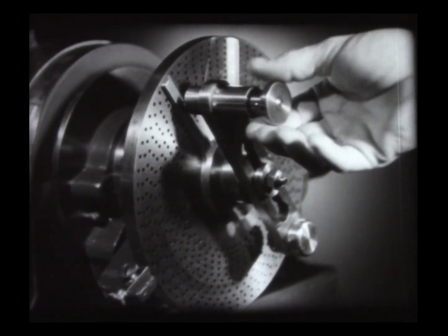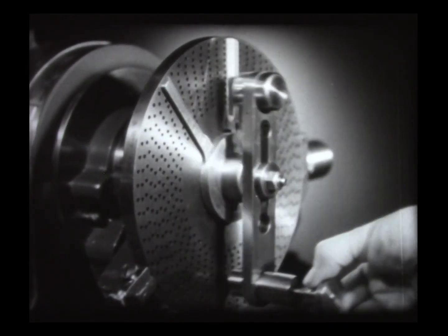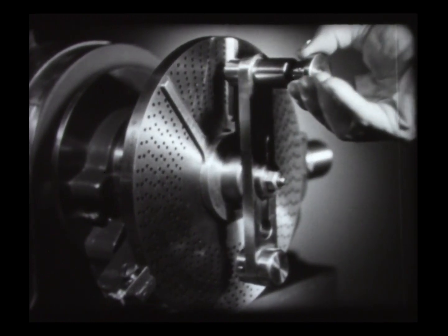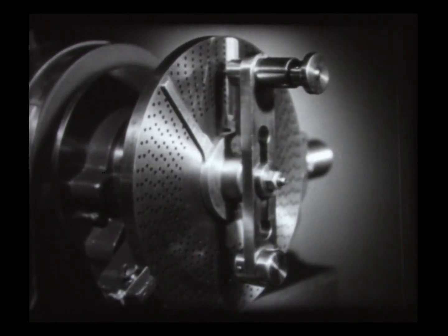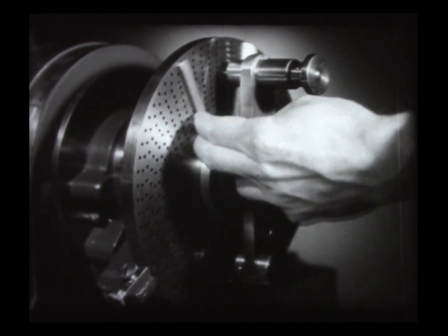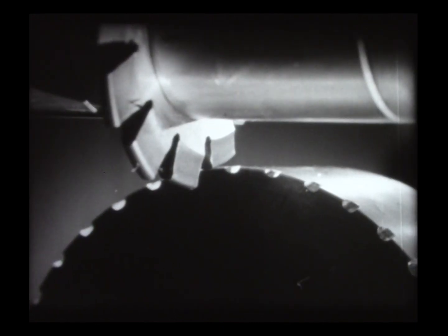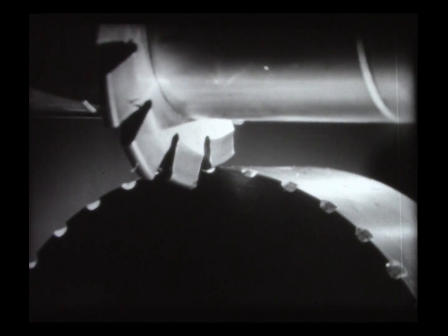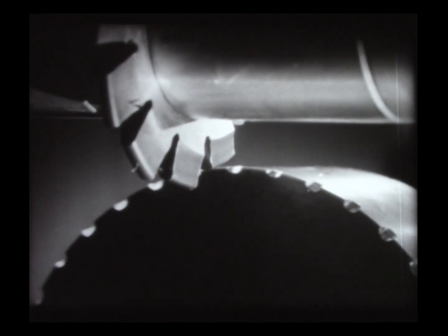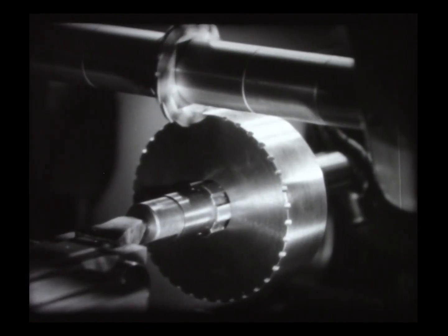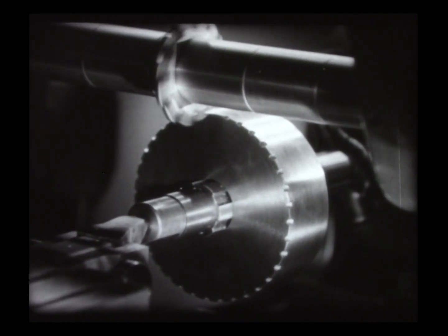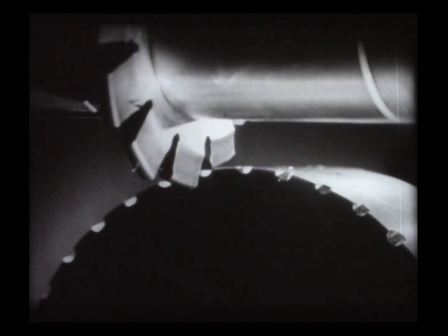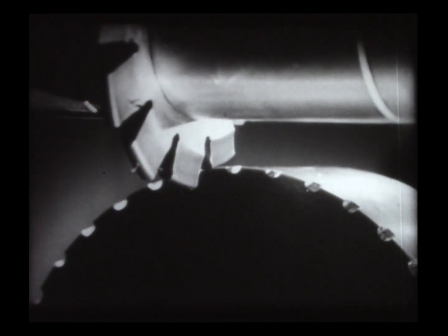The head is indexed for another tooth." Then the cutter is brought up to the first nick by hand to be sure it trues up in this nick. This entire procedure, making trial nicks, counting them, and checking the location of the cutter in a nick, is one of the most important steps in cutting a gear.